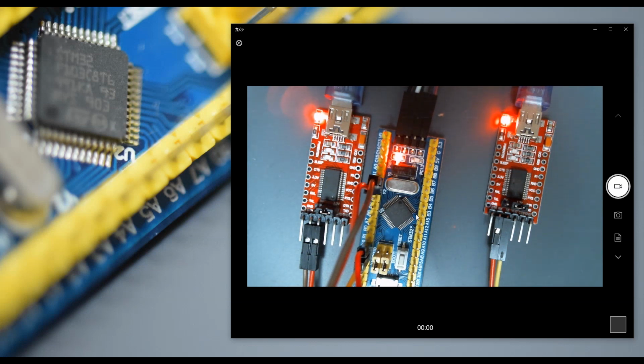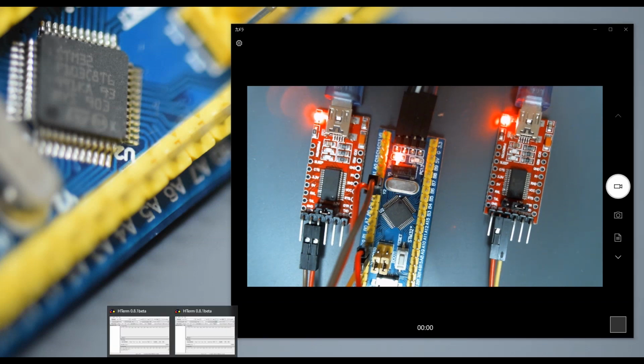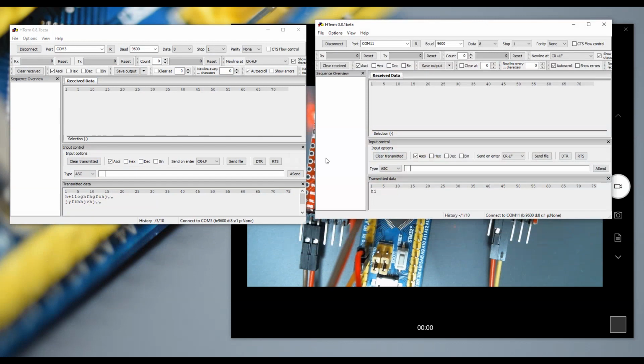Just for information, UART1 on this blue pill is used for the USB connection, not the UART-USB but the USB connection, so it will not be possible to use it for UART communication with a PC.